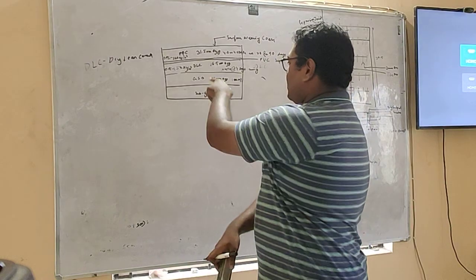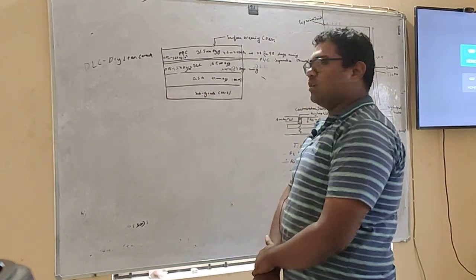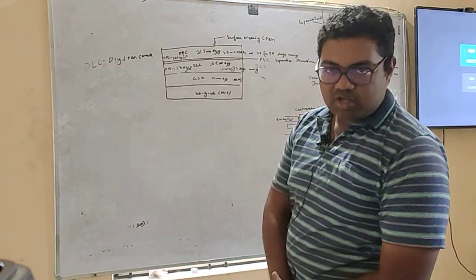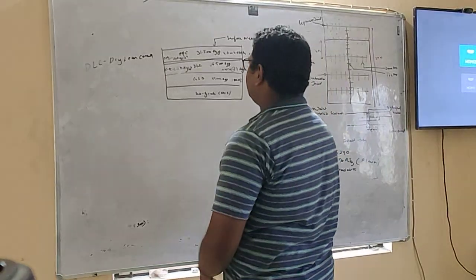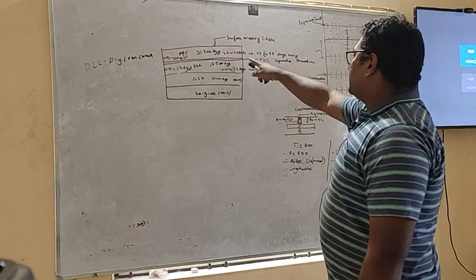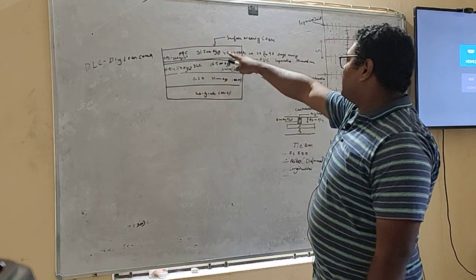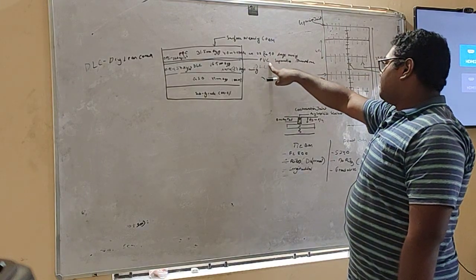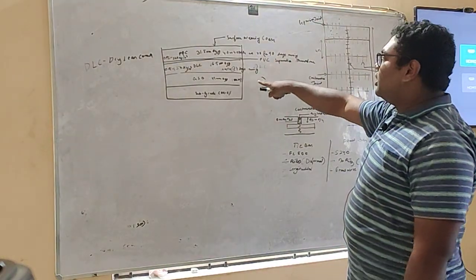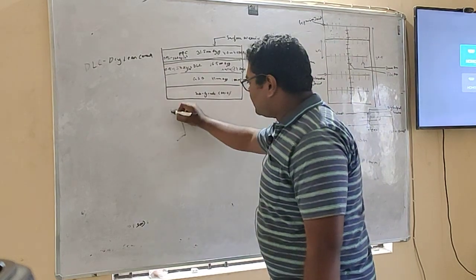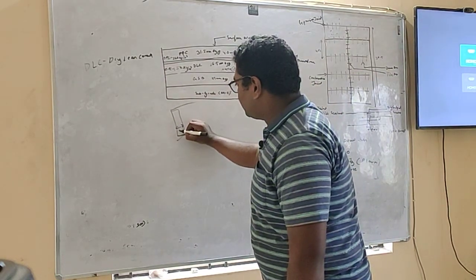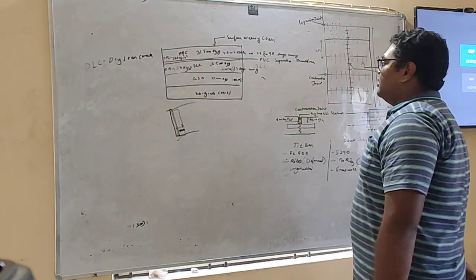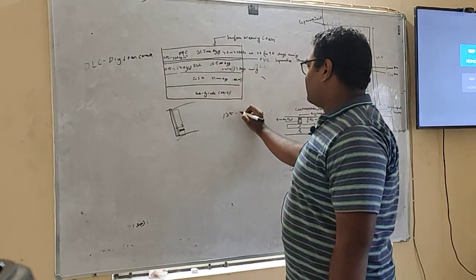After laying our DLC, we will cure it using spraying or sprinkling, but spraying is more preferred. Next, we will move to our PQC. Before moving to PQC, we have to separate our DLC and PQC to prevent passage of water from PQC into DLC. So this separation membrane is made of PVC and its overlap length should be around 300 mm, not exceeding that, and we can stick it with the help of a tape and its thickness should be around 125 to 180 microns.